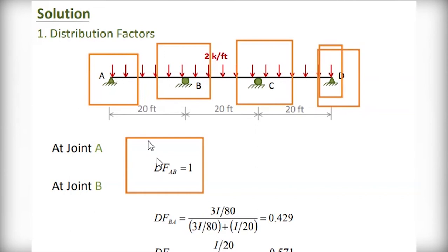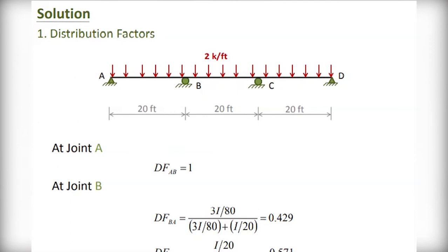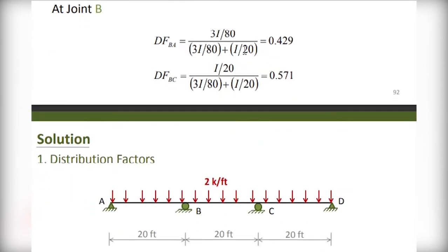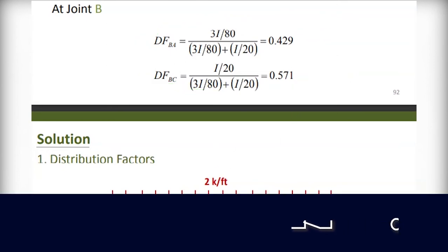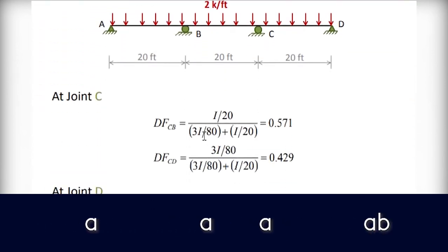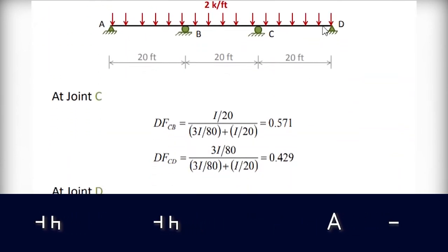Be careful. It depends on the supporting conditions. So joint B, you create on the formula, you get there. But joint A is a supporting condition which is pin support, and here it is pin support. So if it is a pin support, it means its value there should be 1, and its value here should be 1. So the way the support condition is considered matters. So look on the condition. On calculating, you shall have the value here at the joint B. So you can go on with the procedure, and there at joint C, as I said, joint C is the same as joint B. You can calculate by the normal procedure.